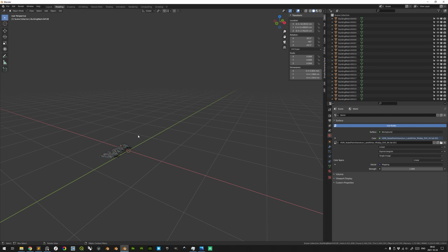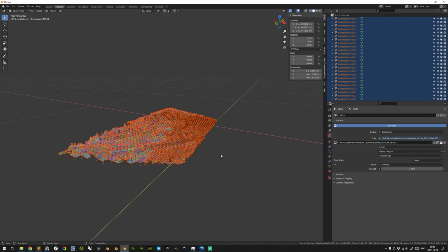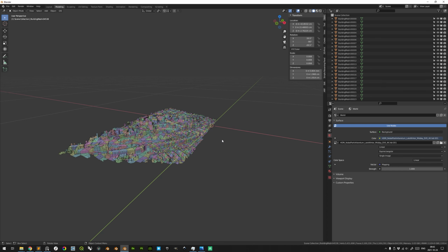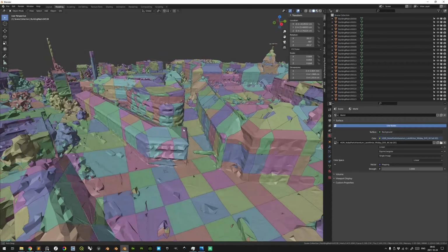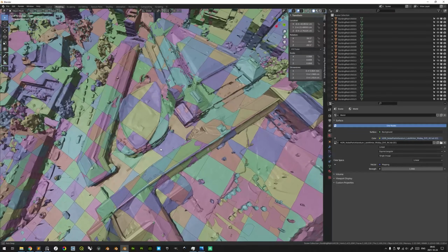And to zoom in on these, one could press A on the keyboard to select everything. One noticed that it was quite sluggish, so perhaps that's not the wisest maneuver to make. But having already selected all those, we can press period or comma on the numpad keyboard. And we can zoom in here, and I'll hold Alt and press A to deselect. And this looks like expected.